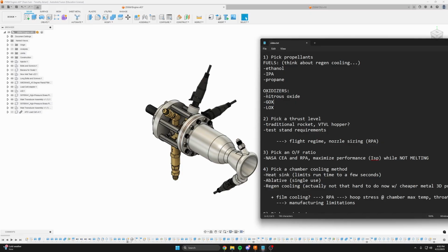And of course, you have similar problems with nitrous oxide, but you're going to be using the liquid phase of the nitrous, so it's a little less sketchy. The activation energy is a little higher for something bad to happen, versus GOX, which is already a gas. But if your mass flow rates are low enough and you're willing to work around that, that's another good option.